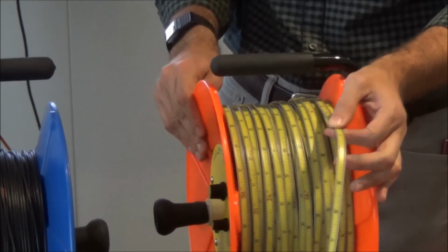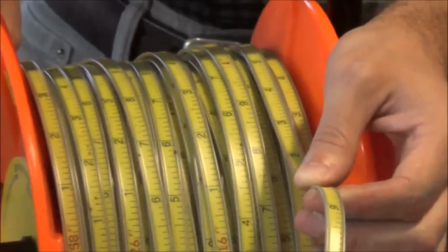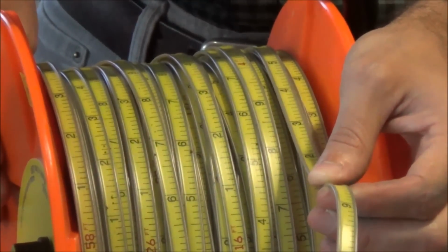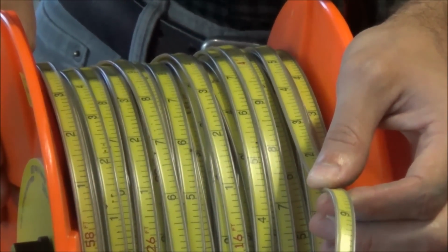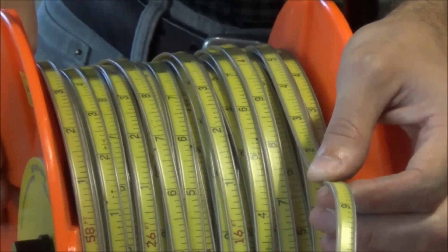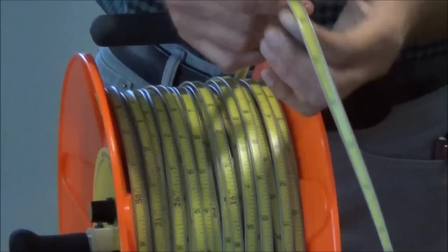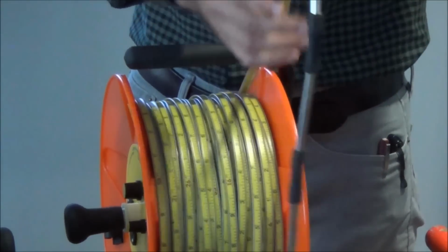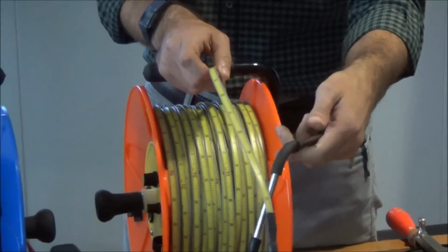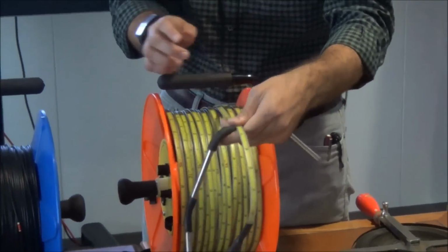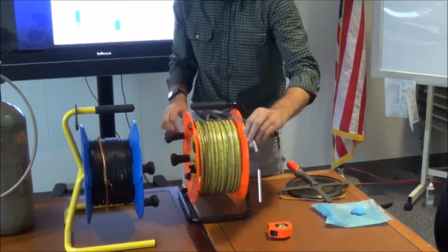And so it gives very precise water level measurements. We don't like to use this in wells that do have pumps because if it gets caught down the well, you have to cut the tape. It's very hard to get it back out. And so that's a big issue, and these are expensive. Another issue is the weights that come with this are kind of large, so you may not be able to get them into some access ports. But this is a very good tape for wells that don't have pumps.